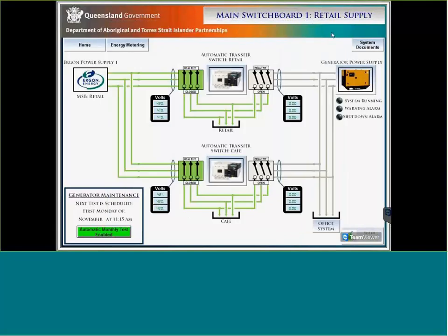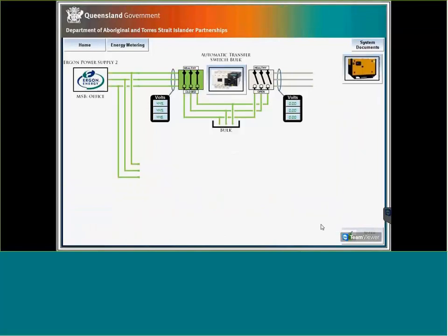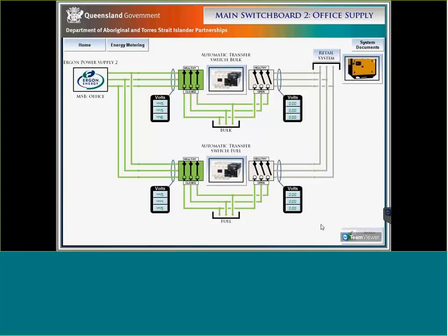We also used some of the power of the emailing and scheduling inside of Indusoft to do a monthly test. You can see down the bottom there we've got a general maintenance tag. In there it shows what month and what time, and it sends out a couple of emails before the generator starts and during the test, to basically do an offload test off-site. We thought that feature worked really well.